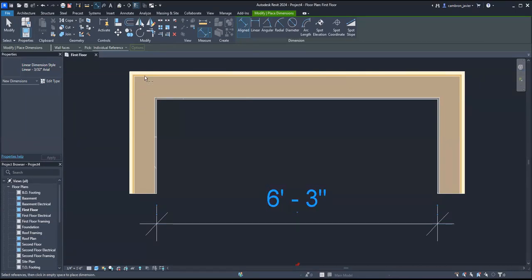So when we're building this out, it sometimes is better to dimension to the studs. Now, when we're talking about interiors and the building's already up, and we're just making some minor changes from the interiors, that means the drywall is already up, and so the contractor is going to measure from the actual drywall, not from the stud.